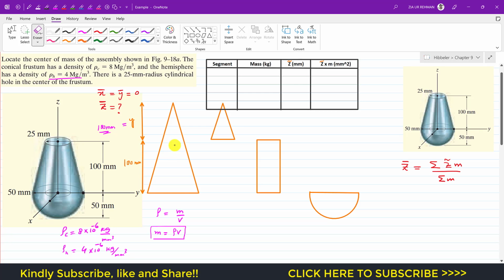So now let's say that this is our segment 1, the full cone. So let me write that the full cone is segment 1. Then we have to find the mass of segment 1. So the mass of segment 1 is m1, and that is the full cone, and the density of the cone is this rho c. That will be rho c times its volume. The volume for the cone is, as we know, 1 divided by 3 pi r square h. This is the volume of the cone, remember.